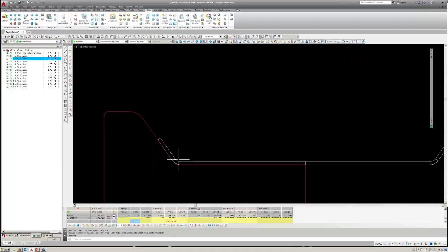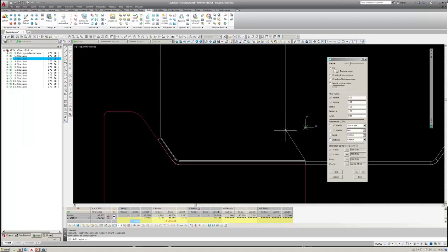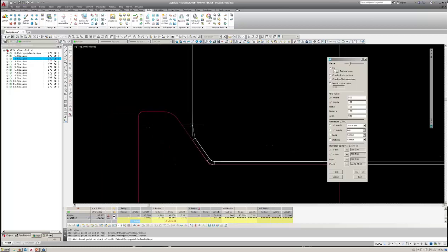So now to creating the top roll, same principle, create roll again, pick the first element here and project in this direction and across to the middle. Okay, so I don't need to add anything here, so I'm just going to right click to give me the none, or press enter. And on this side, of course, now I need to extend. So E for extend. And rather than now select anything with control, I'm going to make it so the diameters meet.